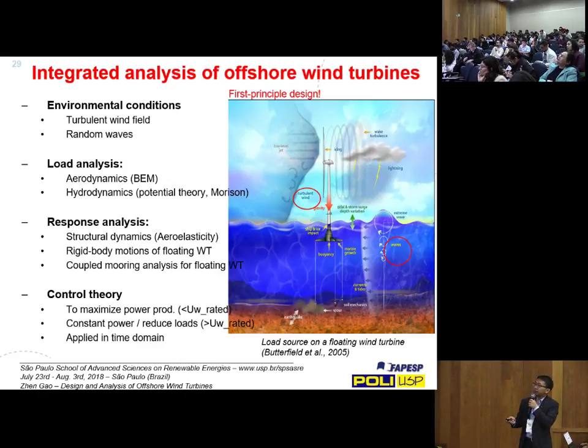Another point is that we have to do response analysis, to get the response, that means the motion of the platform and also the structural response, deformation of the blade and so on. Another point I want to mention is that you usually have a control system which applies in time domain, because it depends on the variation of the speed and so on, or torque. So this analysis is preferably carried out in time domain in order to capture all of these effects. So that is also an important issue.